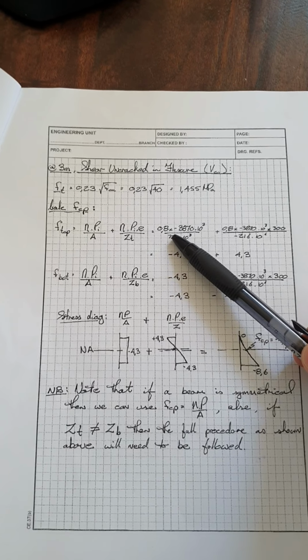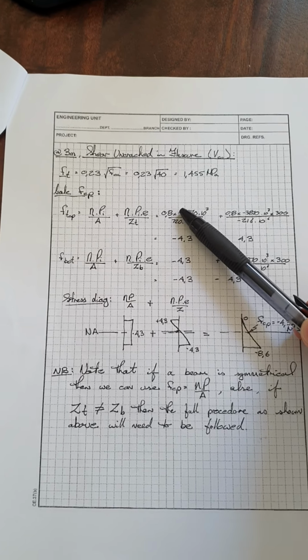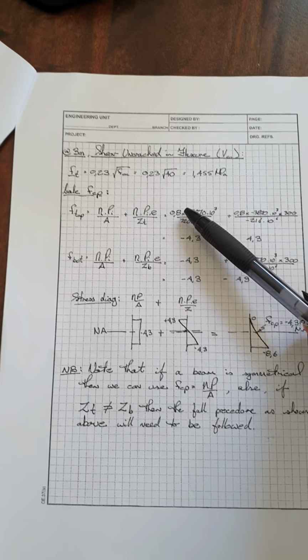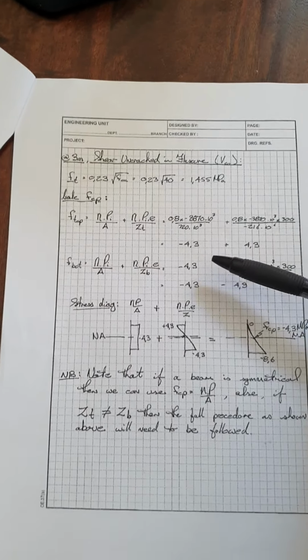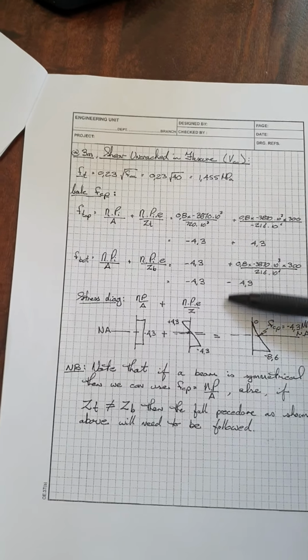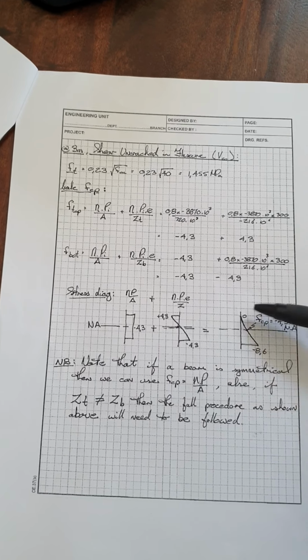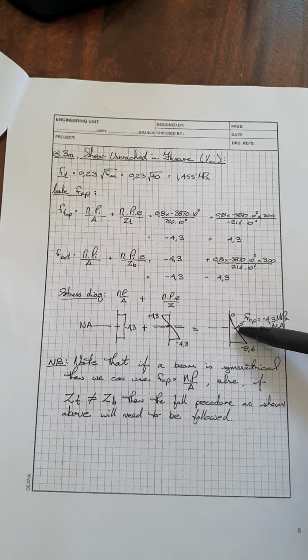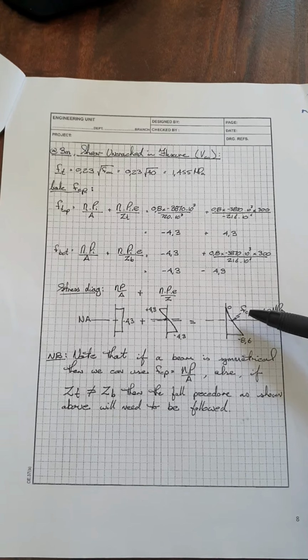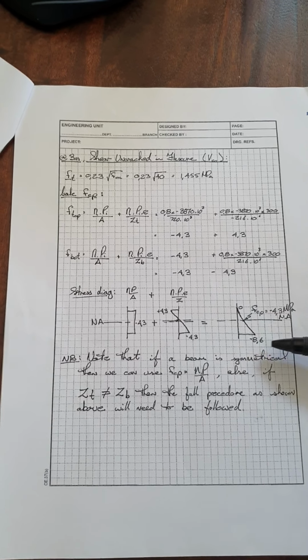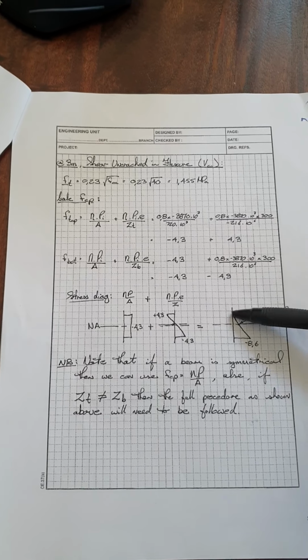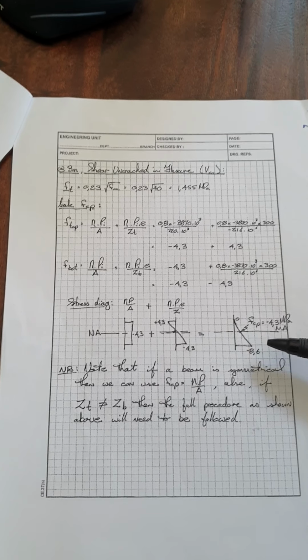In a test, I would possibly have given you a P effective at that point. Bear in mind, if I give you a P effective, you do not need to calculate any further losses. This is quite straightforward. One gets a normal stress diagram, and we calculate FCP at the neutral axis. This example, of course, is a symmetrical beam. So FCP is halfway up, very easy to calculate.